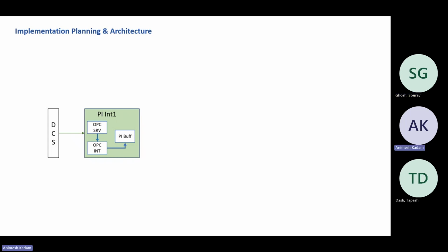Look, in the DCOM setting, what you basically do is allow that particular user to communicate with your OPC server and collect the data, make groups. It means create groups of tags, then pull the data from the OPC server and collect it on this system, from the OPC server to your interface system.